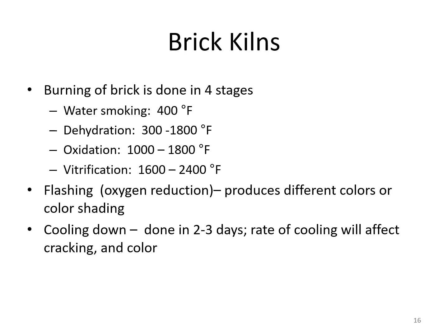If you ever wonder how those bricks have that reddish black look, and it shades, that's how it's achieved, by doing flashing. And then the cooling down time, it takes 2 to 3 days for the bricks to cool down, and the rate of cooling will affect the cracking and the color. As a general rule of thumb, you get less cracking when the cooling takes longer, like 3 days or 4 days. The cracking is more evident when you cool them a lot quicker. So that controls that, and it has some influence on the color as well.